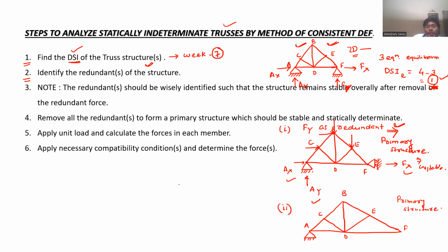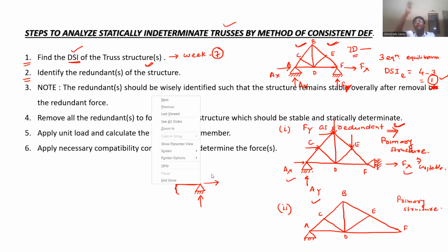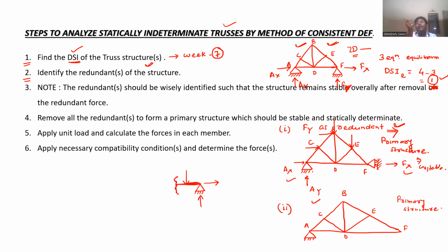Hinge. When you are providing a hinge, how many reactions are you getting? You are getting 2 reactions. Reaction means what? Just understand. If you are applying some load and this is a structure, let it be any kind of structure, this point, apart from rotation, cannot move neither in x direction nor in y direction. And we are least bothered about z direction because it is a 2D structure now. So z direction is ruled out. It cannot move in x direction and y direction.